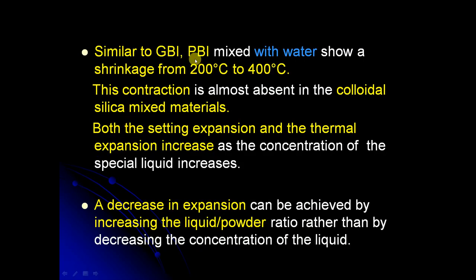Similar to GBI and PBI, that is gypsum bonded investment and phosphate bonded investment, mixed with water they show a shrinkage from about 200 degrees Celsius to 400 degrees Celsius. This contraction is almost absent in the colloidal silica mixed material.